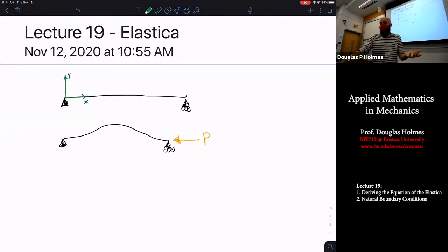And that's what you do in mechanics of materials. You derive the equation of the elastic curve. But what we don't tell you is that you derive the equation of the elastic curve entirely in Cartesian coordinates because we're assuming small slopes. We do tell you we're assuming small slopes, but the consequence of assuming small slopes is that you're living in a Cartesian coordinate system. You're not really following the coordinates that apply to the material.